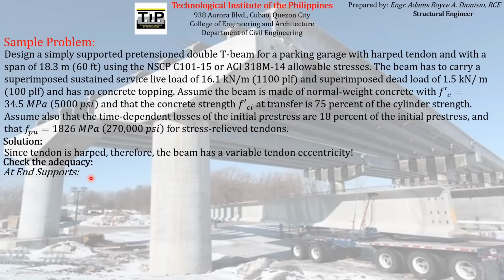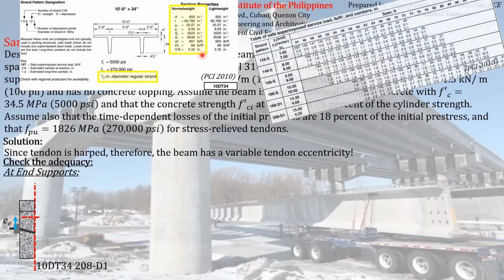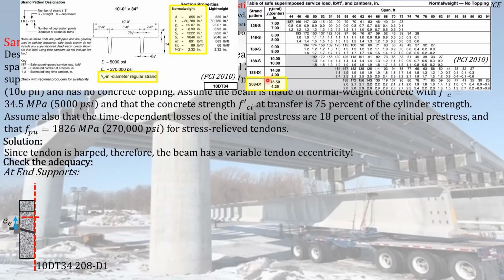So again, starting the checking at the end supports of the section that we have chosen, which is 10DT34 with strand pattern 8-D1, which has these corresponding properties here and properties here that can be found on PCI 2010.